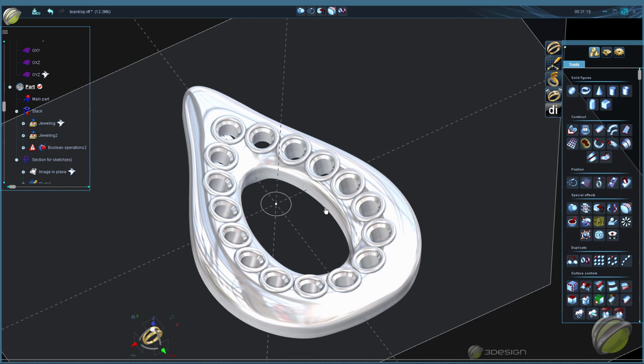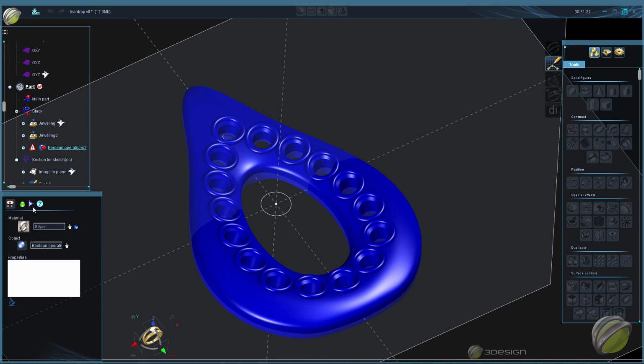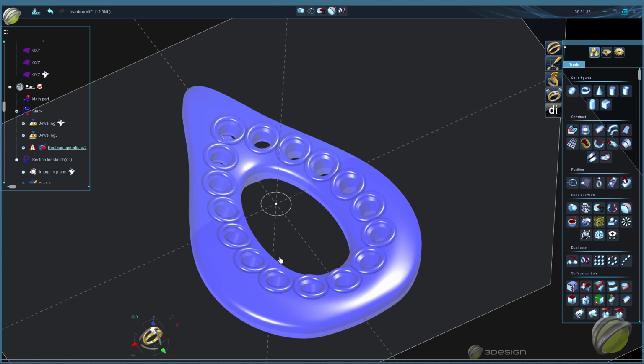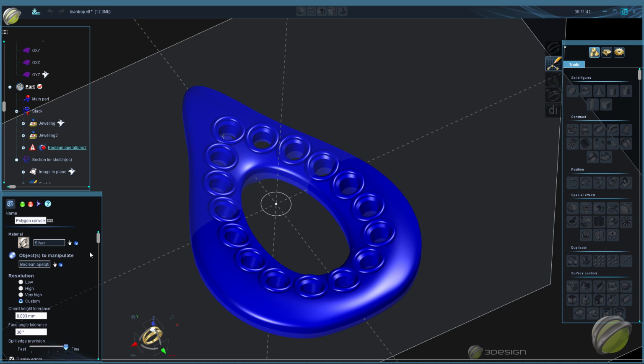But anytime we have a warning, we're going to check, run your part doctor. So yeah, it is solid. We'll check the microscope. Violation of tolerance. It's kind of expected when it has to move geometry around. Violation of tolerance is not necessarily an error, just means that a couple of edges are slightly out of that thousandths of a millimeter tolerance range. That's okay. I always like to check with the polygon conversion as well. Use the same settings you use in your STL export. Check the quick tip video if you're curious about these settings. And we'll just preview that. We only use this tool to preview for bad edges. If this is going to convert without any bad open edges, we're good to go.